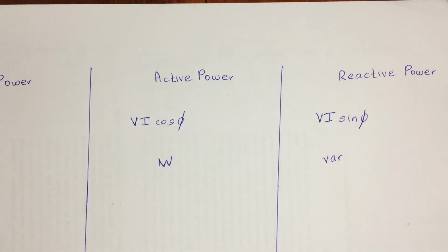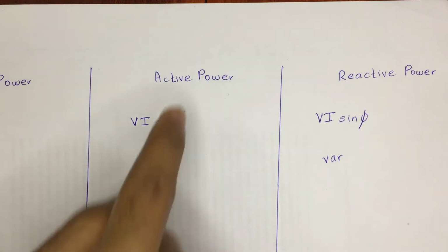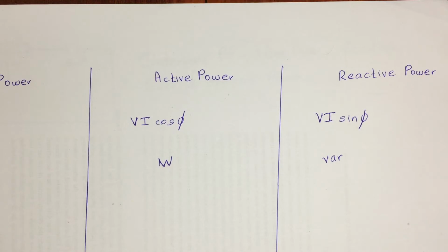Active power is the power we are going to get from that total circuit, because actually we knew that if there are three elements in a circuit, let's say resistor, inductor and the capacitor. If we have the three elements in an AC circuit, we can directly tell the active power is gained from the resistor only, which means the power we are going to get from that circuit or that element would be the active power. The reactive power is stored in that circuit and returned to that circuit always.